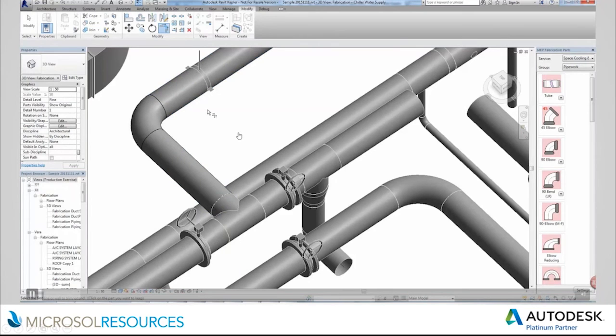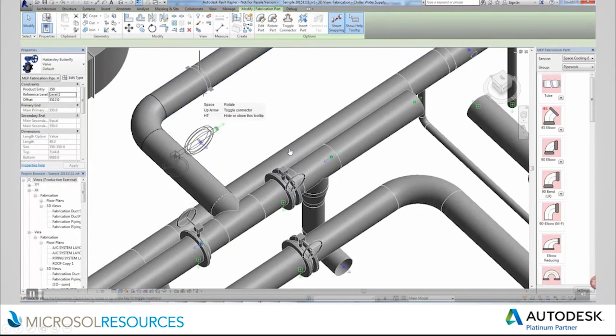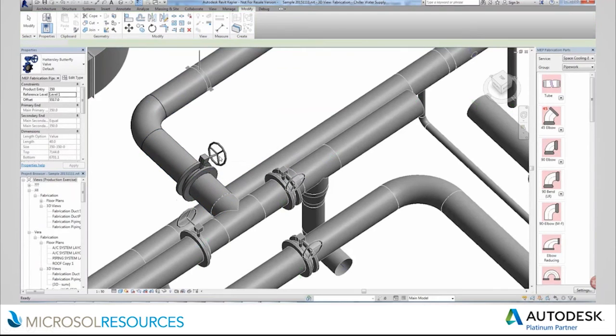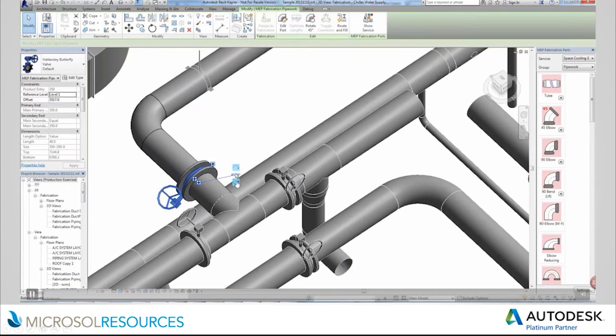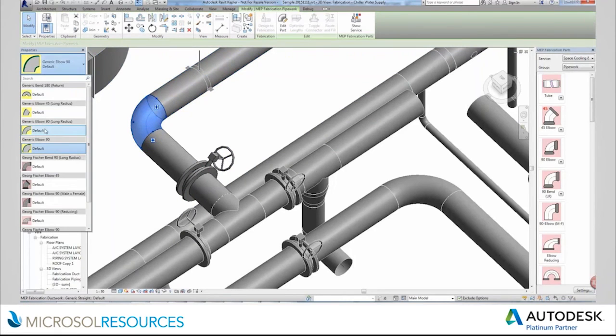The other thing, like I said, that is shown in this video is basically how we can add in things pretty easily. Like I'm adding a valve in line right to this piece of piping right here. By using the controls for the angles, I can set the angle for the valve itself, with different options, 90s, 45s, and so on. Makes it quite easy. And if it needs to put in additional flanges and things like that around the part, it will do so. So you can see where it put in these flanges automatically. It knows the dependencies based upon the databases that it needs for fabrication.